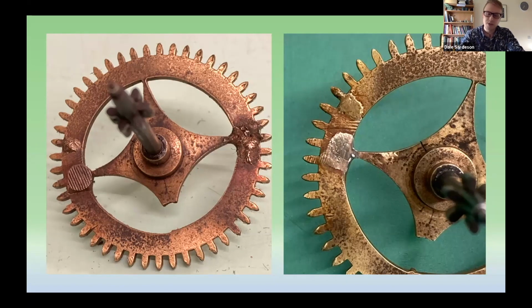I think that many restorers or repairers would be sorely tempted to replace this wheel. It kind of looks a bit risky to leave it. But as Jonathan mentioned in the last of these sessions, conservation is about having minimal impact on the materiality of the object. And I felt that with a bit of reinforcement with some soft solder at what looked to be the most at-risk crossing, which you can see in the post-repair picture on the right there, this wheel could continue to serve its function with minimal intervention.